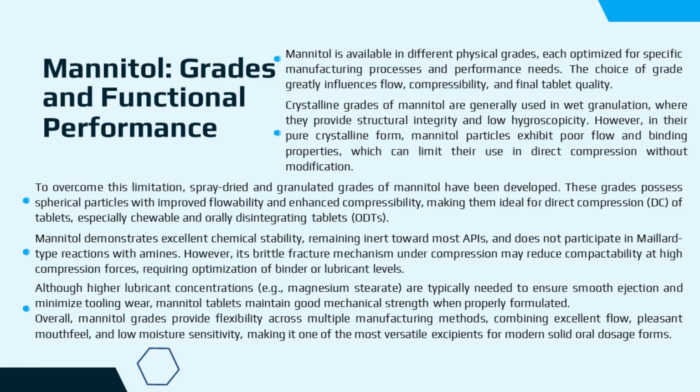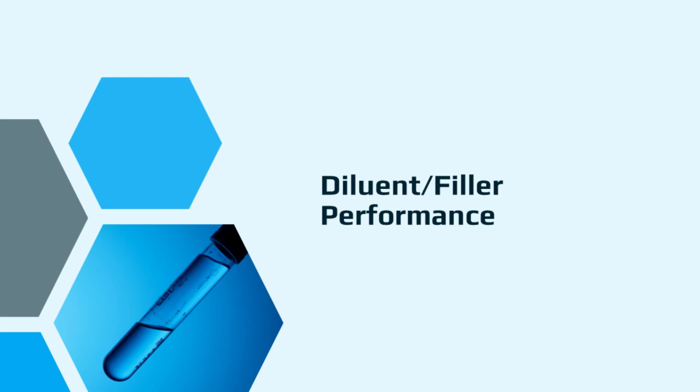Overall, mannitol's grades provide flexibility across different manufacturing techniques, combining excellent flow, pleasant mouthfeel, and low moisture sensitivity, making it one of the most versatile excipients in solid dosage formulation. Now let's compare the performance characteristics of the major diluents and fillers used in oral solid dosage formulations.